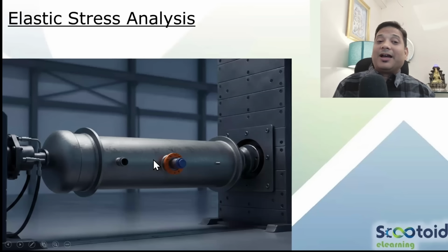Will this pressure vessel, if I'm just trying to pull it from both the ends, very similar to what we do for the round bars, behave in the same way? The answer is no. It's a complicated shape, isn't it? In the majority of locations in the longitudinal direction, you'll have the primary membrane, no doubt about that.